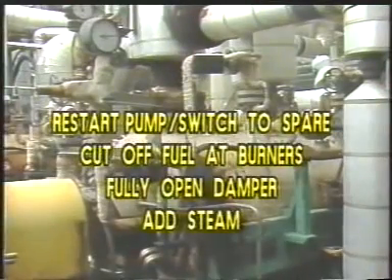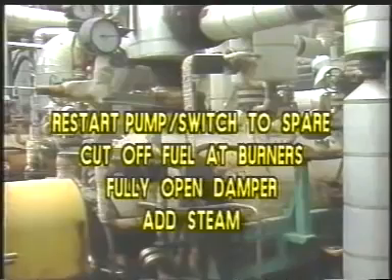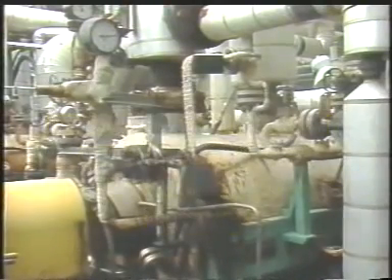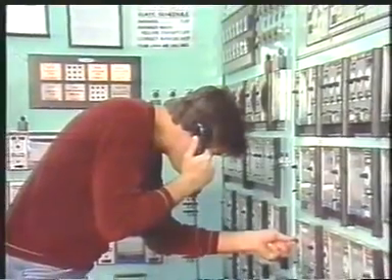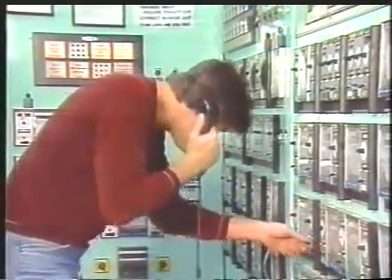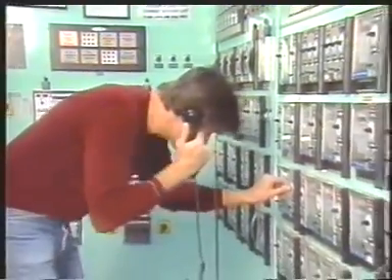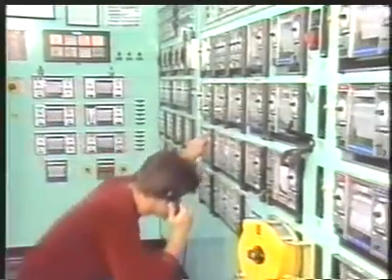Your first reaction should be to restart the pump if possible or go to a spare. If you can't get the flow started immediately, you'll need to stop the input of heat by cutting off the fuel to the burners. The damper should be opened fully to allow the maximum amount of heat to leave the furnace. And steam should be added, which will have a cooling effect on the furnace. By cutting off the fuel and removing as much heat as possible, you minimize the chances of furnace damage. Once the situation stabilizes, you would want to call in maintenance and have the defective pump repaired.